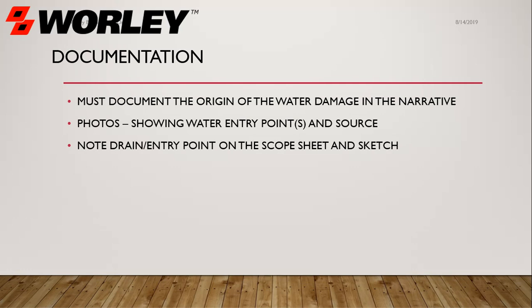Photos, that's the second component. We want to show not only the water damage, but the source of the water. Where did the water discharge come from? Was it a sewage line? Was it a freshwater line break? Was it a supply line? Was it an appliance? So we want to make sure that we are really documenting everything that we possibly can here.